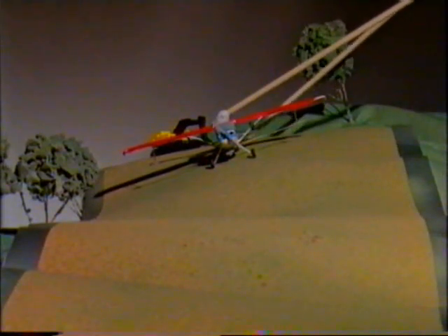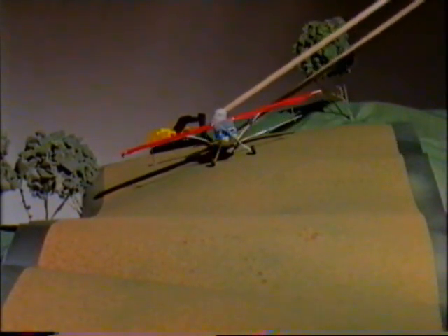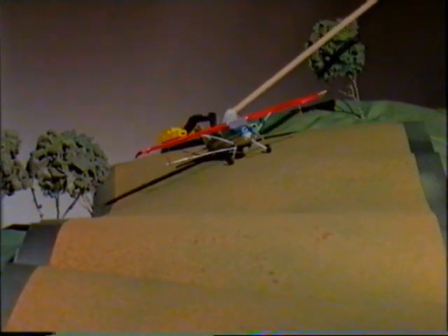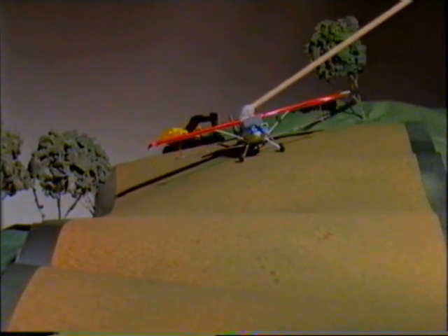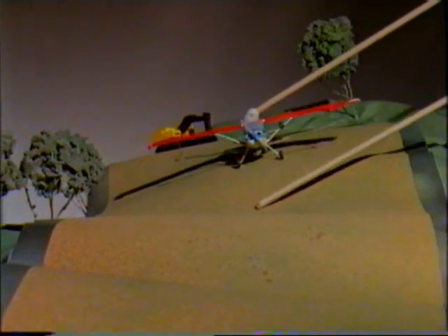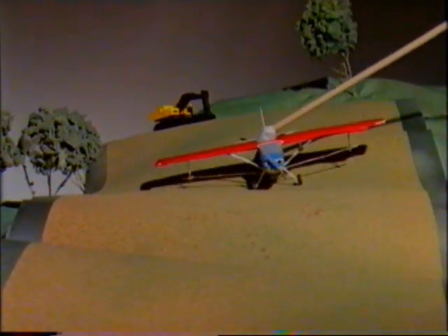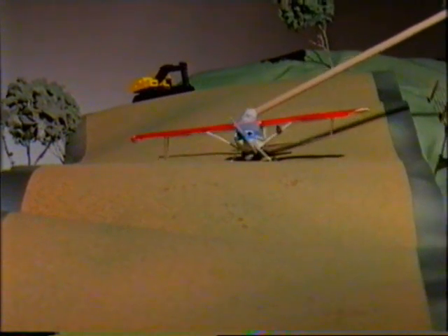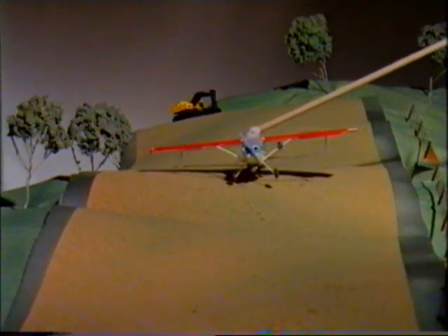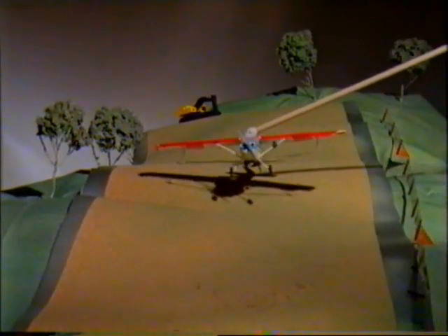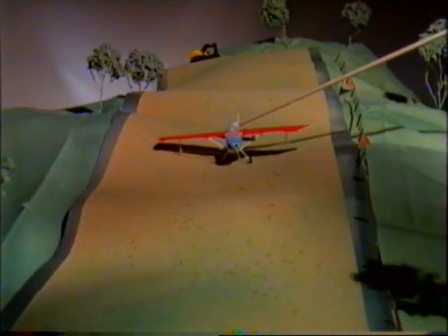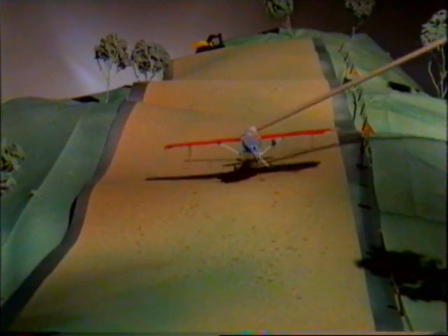The effect of the transverse gradient on a tailwheel aircraft is that the aircraft will tend to want to swing up the gradient. This will effectively increase the takeoff run because we'll have to use brake to keep it straight. The effect of the longitudinal gradient is that the aircraft will accelerate quicker, so it will shorten our takeoff run. On undulating strips, just be wary of premature liftoff. Aircraft may lift off and then settle back on the ground, and this will effectively increase the takeoff run.